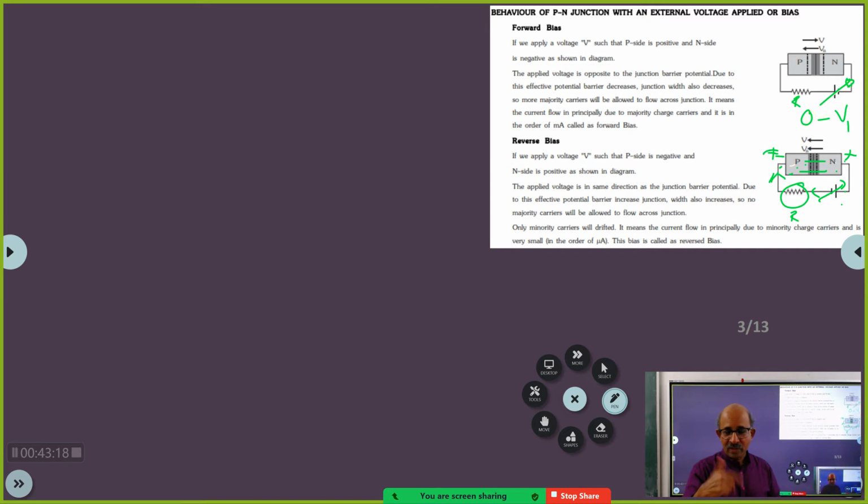That is another thing. You see in the Himalayas and the snow-covered mountains, there is something called an avalanche. One snow boulder starts coming down, it will hit one more boulder, and that boulder will split into two, and that will hit something else, so there is a chain of such collisions, and you will see a whole mountain as if it is coming. Avalanche. Yes, sir. So the avalanche phenomenon can take place within the diode, and the diode can get destroyed permanently. That is one thing.